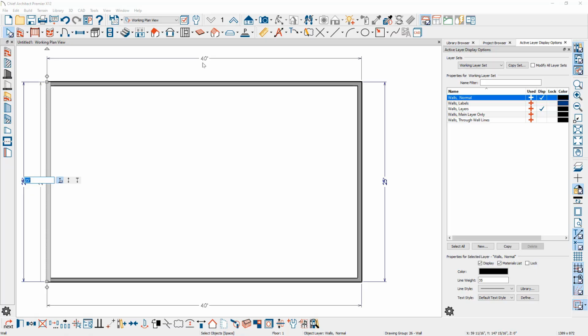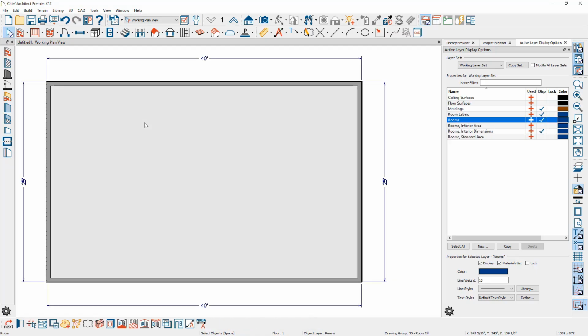As you create your floor plans and set your dimensions, I usually encourage you to work in a clockwise manner. When you get around to the other side, then your dimensions are consistent and you haven't moved a wall in a direction that would offset as you have begun your process. When you create 4 walls, as I have here, you can click in the middle and a room is formed.